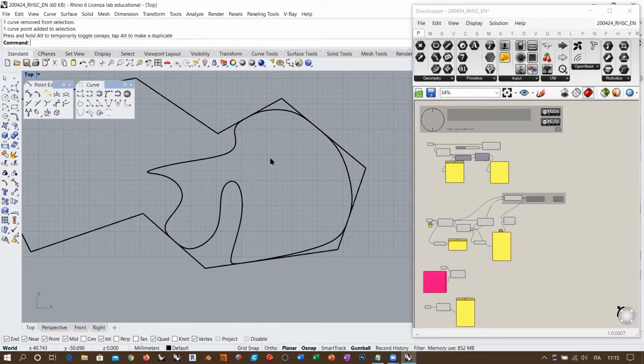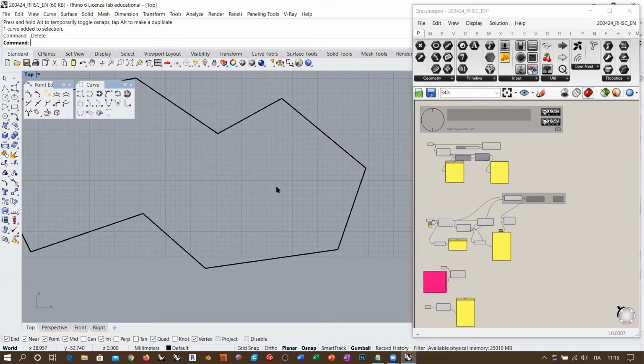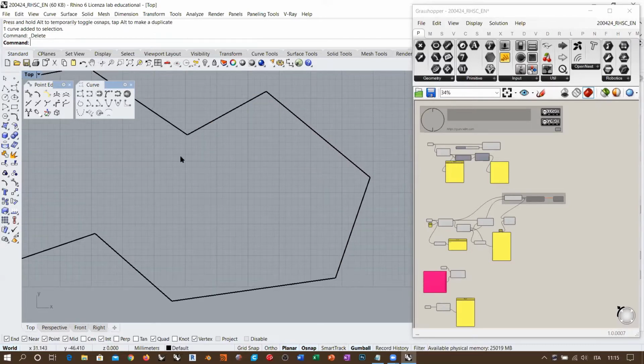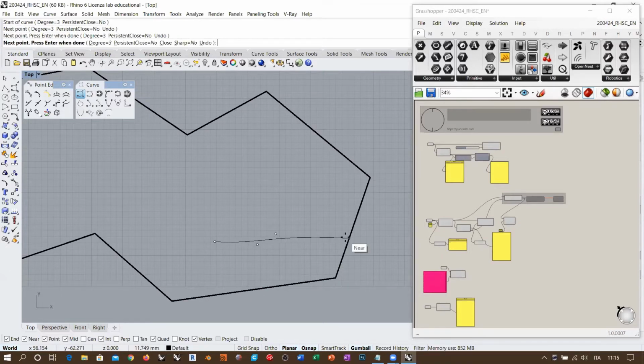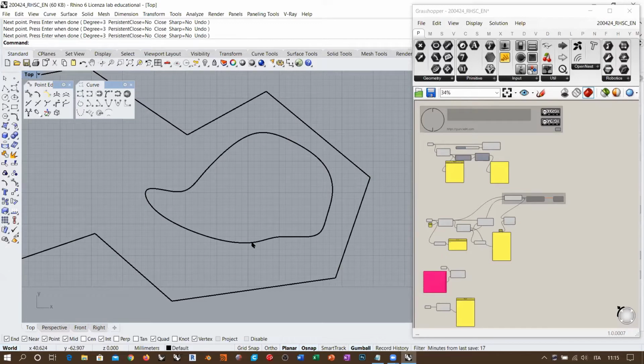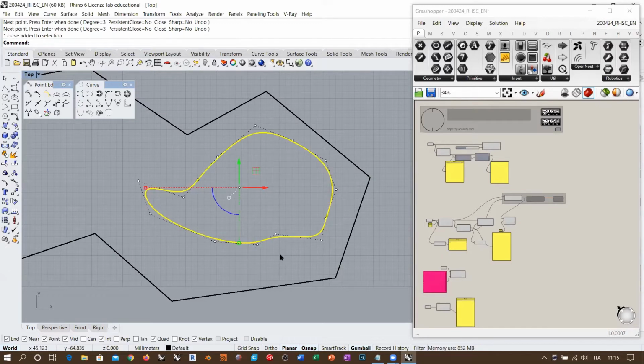Okay. So, for example, if I want to create a curve which is tangent to this area of this polygon here, I can also create a curve like this. I want this curve to be tangent to this line. Well, I need 1, 2, and 3 control points. I want tangency to this one, so it's another 1, 2, and 3 control points. Tangency to this one is another 1, 2, and 3 control points. Okay, and so on. And I can work however I want, and I can close the shape. So I am creating the necessary topology to create the geometric condition that I want.